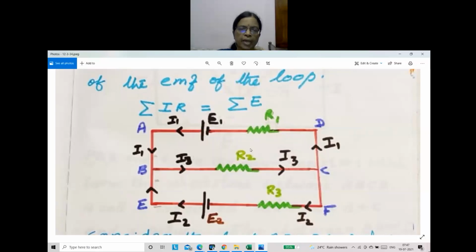Well, first here we are explaining the voltage rule. So here you take this loop. Three loops are here. Suppose we started our motion from here. That means current is flowing from the positive terminal of the battery. The arrow mark is shown away from this. So current flows through this and it can flow along this path. This is one closed path.